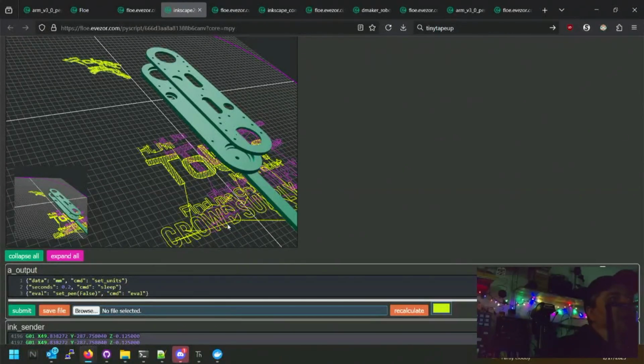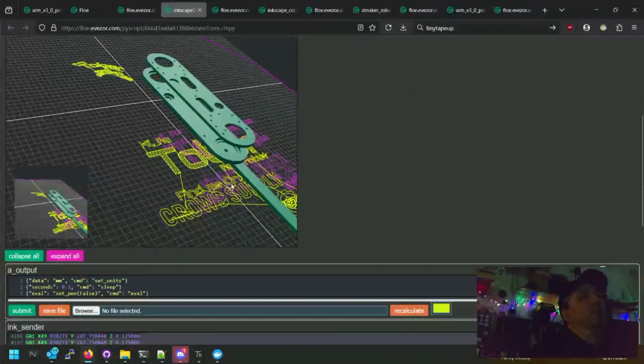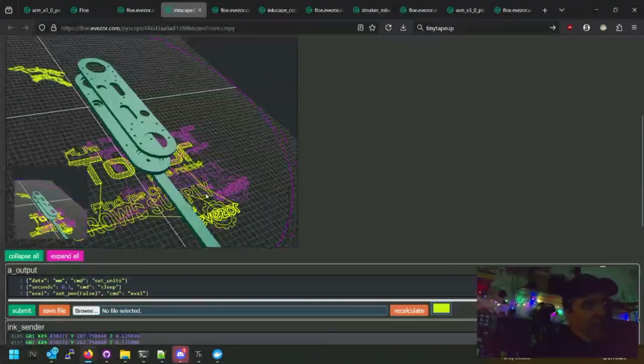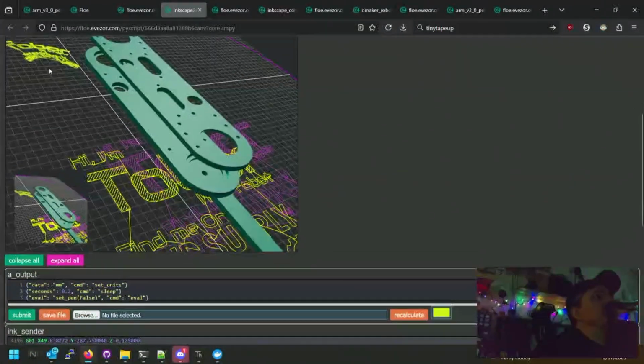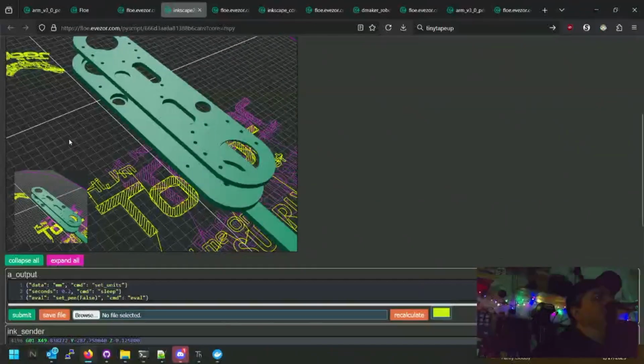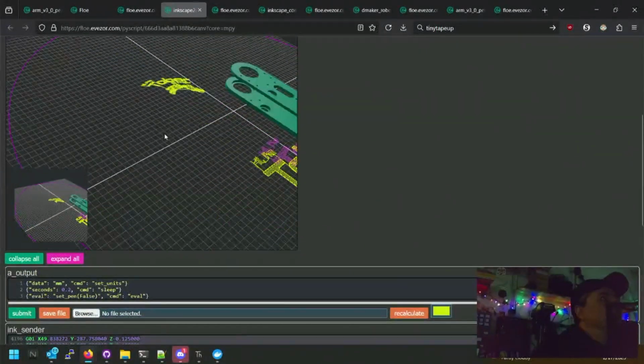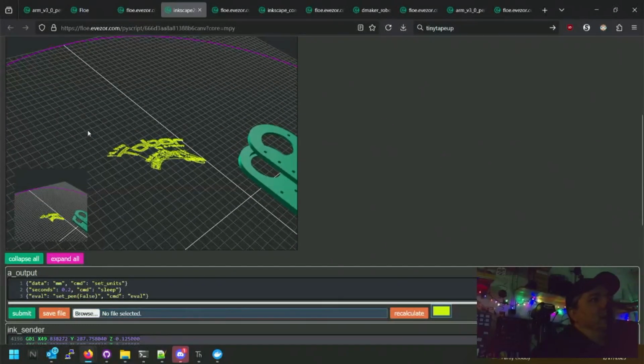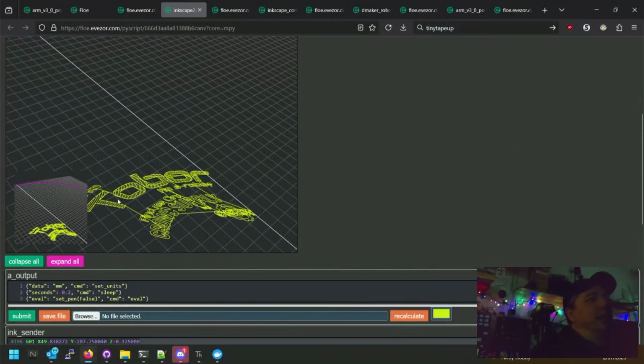So one of the fun things about robots is the fact that there are no straight lines. With a regular Cartesian machine, you're typically setting up something in X, and it's always X, but with robot arms and polar things, there are no actual straight lines. So you have to also tell it where in space and then what kind of rotational angle you want. And it is also neat that even though it is polar, sorry, I'm not very good at doing this on my trackpad, you can see that this is actually the SCARA code.